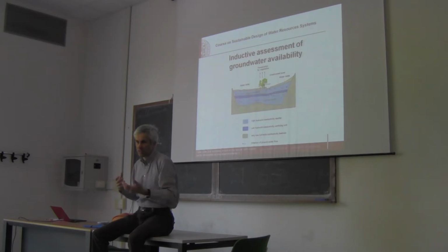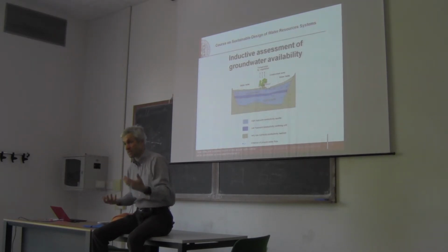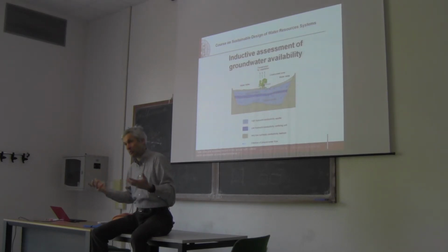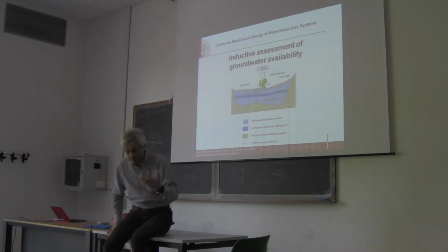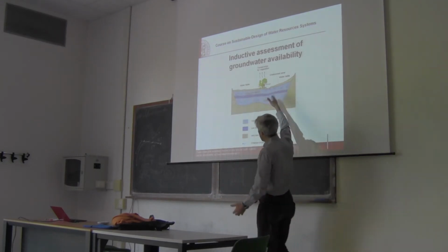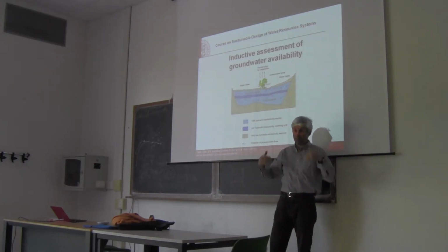In some cases a stress test may be a good option because the aquifer is easy. There are some aquifers that are clearly easy. We clearly identify where water is coming from. We realize that water is just a few months old. So we realize that there is an annual cycle that completely replenishes the aquifer, but in other cases really it's a problem. And you know, in the same region, like the region here, you may have several aquifers at different depth.